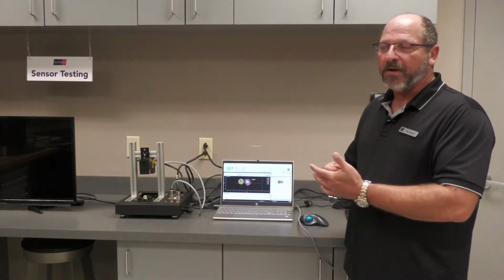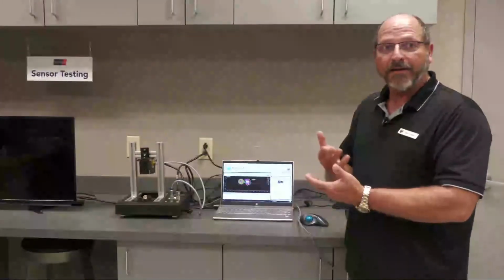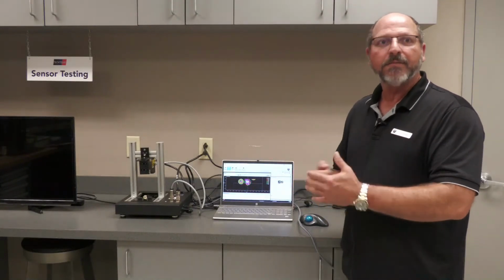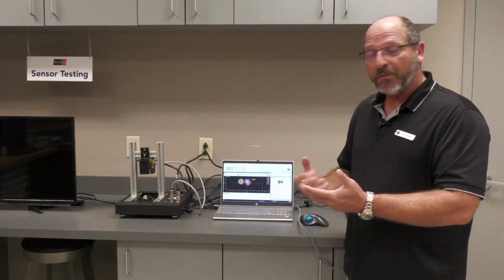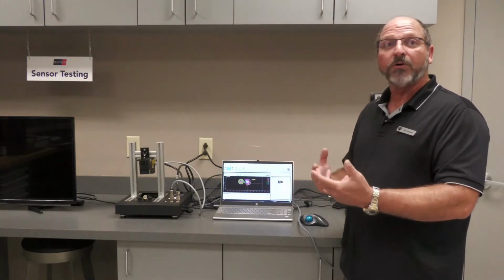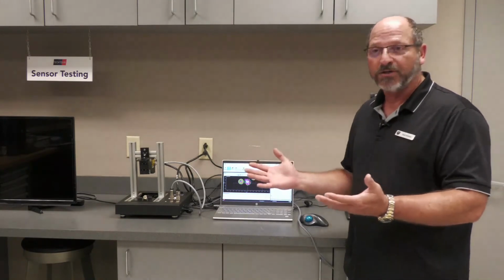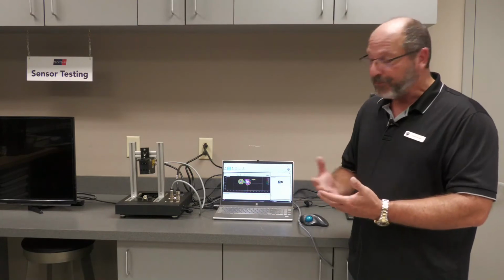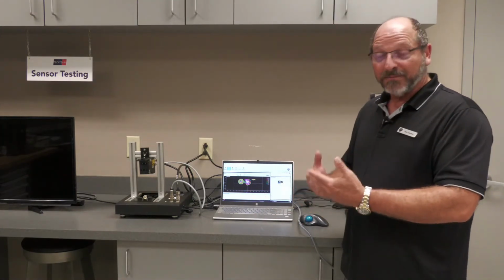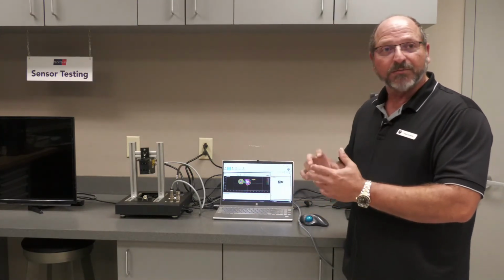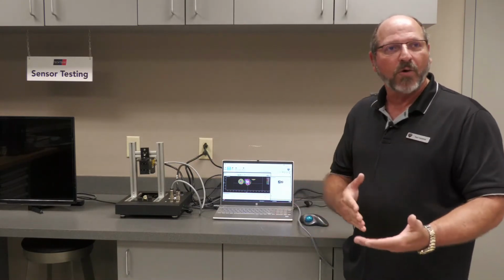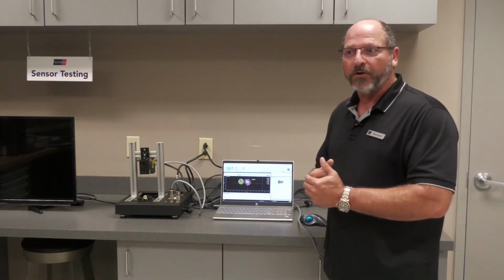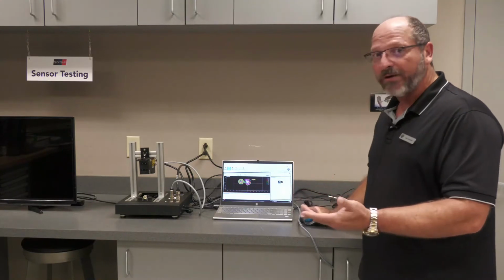But you can set that by size of item, height of item, the area of the item as it comes through. That also allows you to ignore certain things in certain situations where you may not want to make an image of something if it's too big, or if it's touching. It replaces that photo eye requirement and allows you to configure or optimize for the image acquisition of what you want to see.